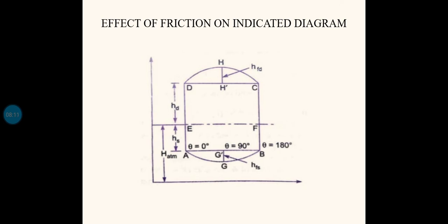And one more thing I have to add is, in the case of pressure due to acceleration of the piston, there was a triangle instead of this parabola, here and at the suction side. But if you draw the triangle, the area excluded from the rectangle is added to the other side. Therefore, the total area of this rectangle is constant. So work done is constant in the case of pressure due to acceleration.